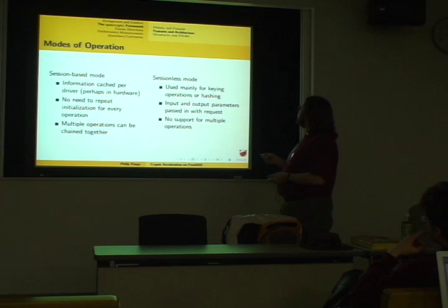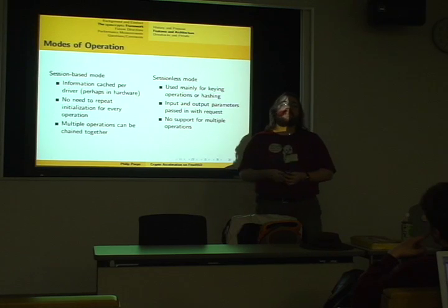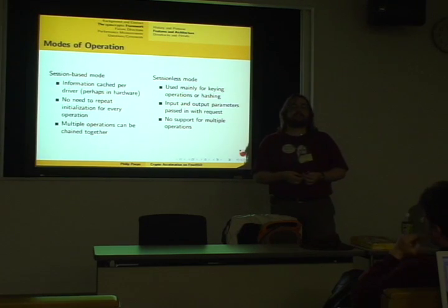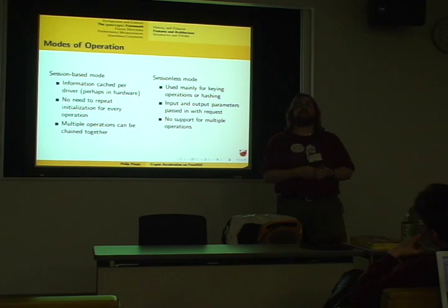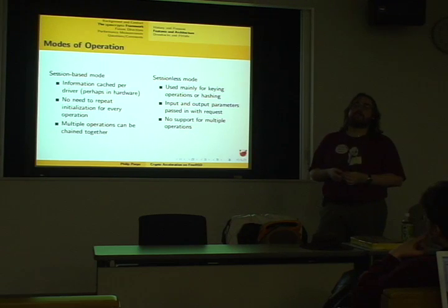There is also a sessionless mode, which might seem simpler, but it's not. It's used mainly for generating keys and for offloading mathematical transformations. Some cryptographic hardware has silicon which can do modular exponentiation or similar operations, which are sometimes faster to do in hardware than in software. And the sessionless mode takes advantage of this.